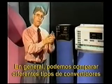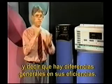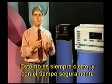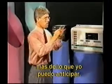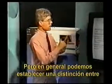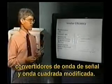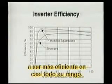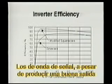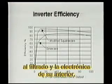In general, we can compare different types of inverters and say that there's general differences in their efficiencies. This isn't always true, and as this tape becomes aged, perhaps different inverters will improve in their efficiency more than I predict. But in general, we can draw a distinction between sine wave inverters and modified square wave, what often are called modified sine wave inverters. In general, the modified square wave inverters tend to be more efficient over most of their range. The sine wave inverters, although they produce a nice sinusoidal output, because of filtering and electronics inside, tend to operate at slightly lower efficiencies.